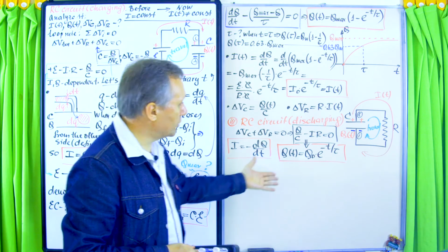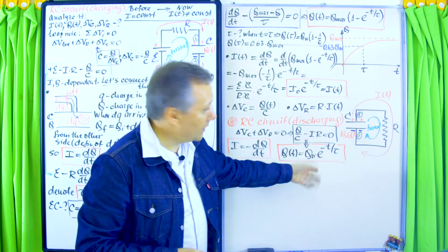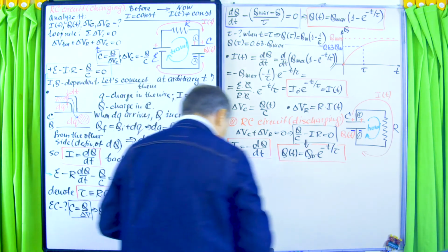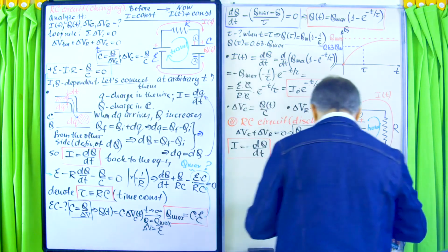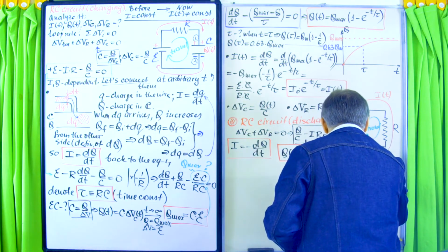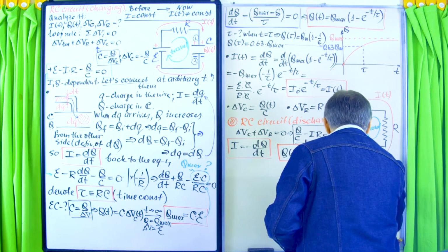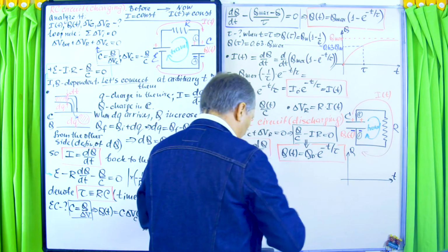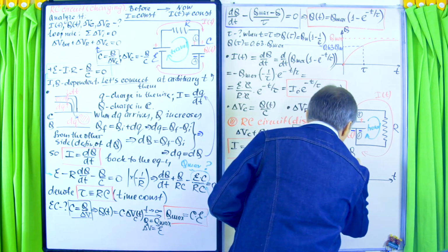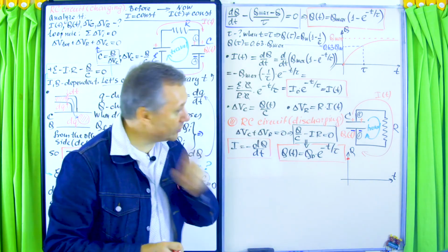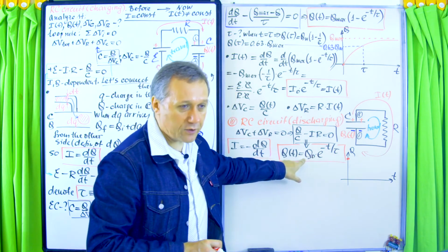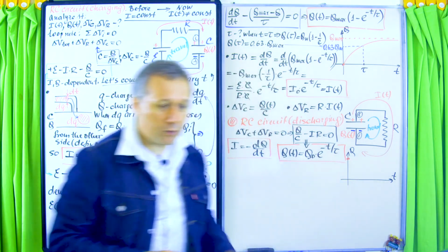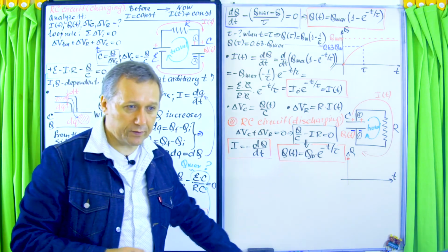And again, if you plot it, you see it's an exponential decay, and the time constant is the same, tau equals RC. All right. So if you plot Q versus time, this will be an exponential decay. At the initial moment of time when t equals 0, charge is maximum, Q naught, and then it decays exponentially, going to 0 when time goes to infinity.